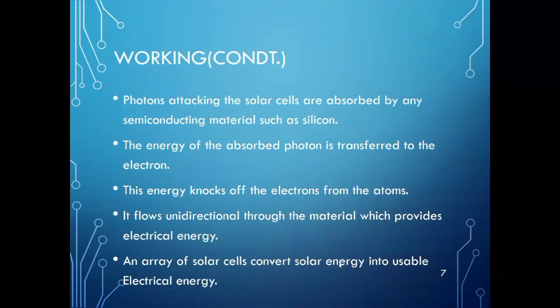which occurs due to opposite poles. An electric field occurs when opposite charges are separated. To get this field, manufacturers dope silicon with other materials, giving each side a positive or negative charge. Phosphorus is added into the top layer of silicon, which adds extra electrons and a negative charge to that layer. Meanwhile, the bottom layer gets a dose of boron, which results in fewer electrons, or a positive charge.